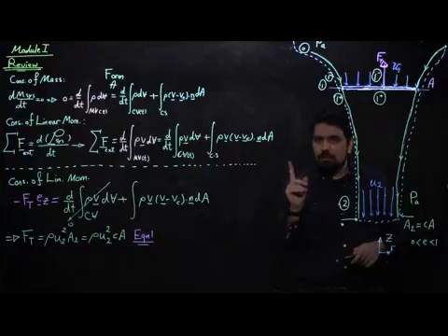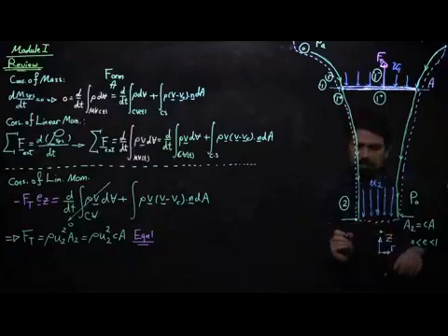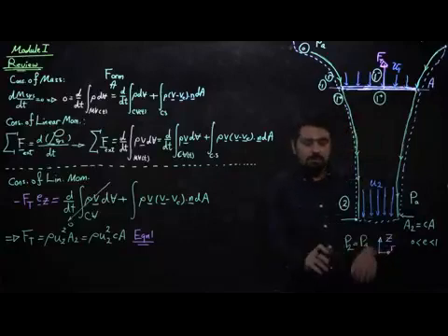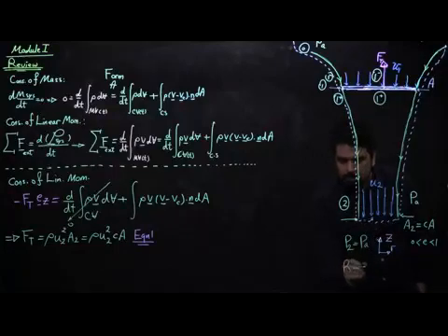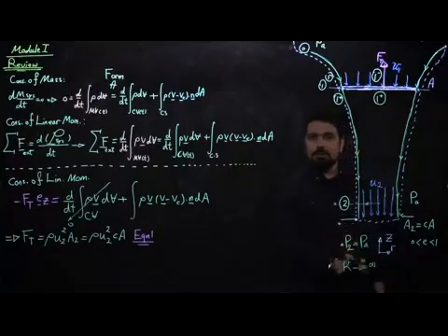But the point that is very important, how I notice that pressure here, P at 2, is equal to P atmospheric, is a concept that we just talked about in our review. Whenever the streamlines are flat and there is no curvature, the radius of curvature is going to infinity. So if I take a point here and move normal to streamlines like this, I'm not going to change the pressure at all.